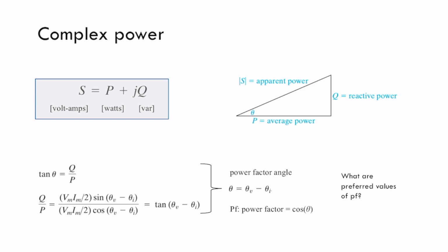So I will come up with an intention, and we call it complex power, the composition of these two elements. P will represent the real value of a complex number, and Q, this reactive power, will represent the imaginary part. And this complex number is what I call complex power. I will show you that this is convenient for me.